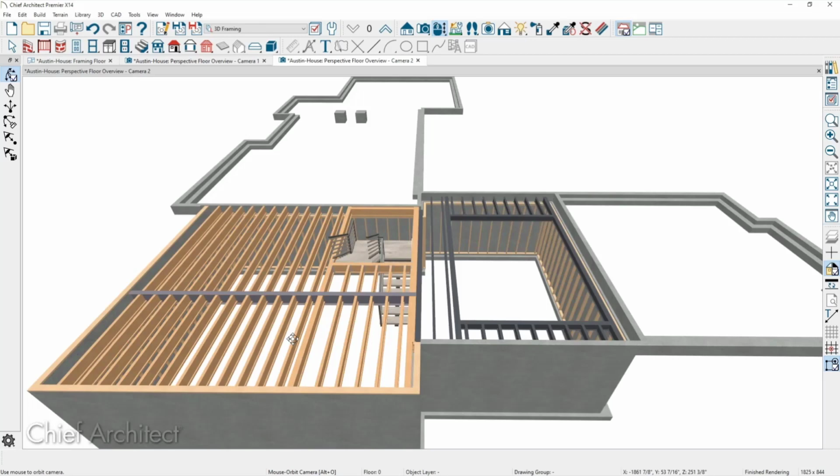And then when you build your foundation with piers, once you've set the dimensional heights of those, I usually just use the copy tool because they've come in at the right elevation. And if you need to modify them based on terrain differences, then you can click on them in an elevation view and adjust them. Okay, so there's really no way of adding that beam to have it automatically place the piers underneath of it when you're building the foundation.